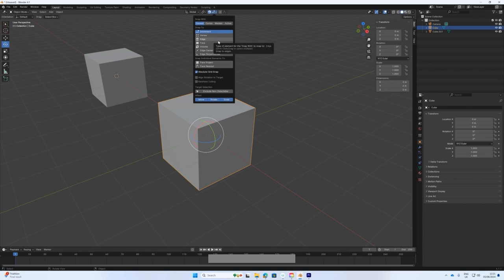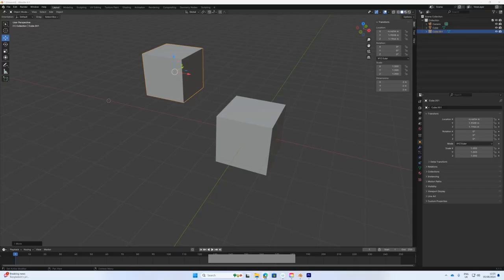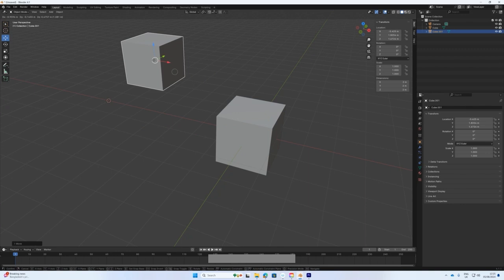But now in version 4 plus, Blender 4 plus, they have what they call a snap base. So I'm going to show you this now. I can turn this off now. What you do is press G. Let's say I'm going to move this guy, so I press G. Then I keep my left mouse button down, and I press B for baby, and I still keep my left mouse button down. Then you can see I can choose here where I want this end.